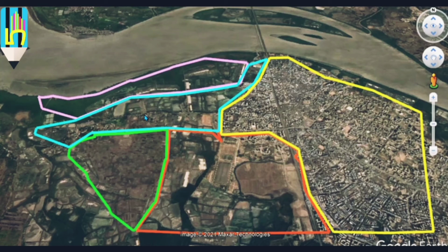And for other areas, we can apply the methods which give us a higher return value of population. So here you learned a new concept: if you are designing a water supply network for an area, we don't necessarily need to give the same factors for the entire area, because if some area is already very highly developed, it has very little growth potential.